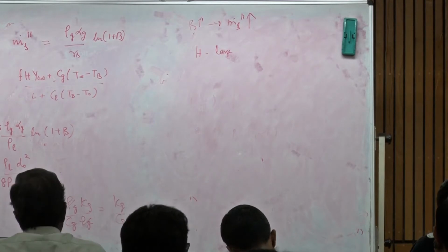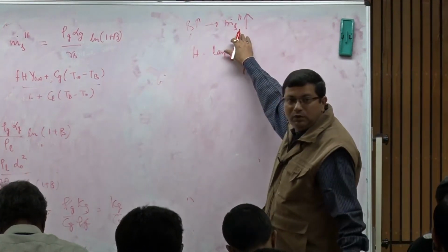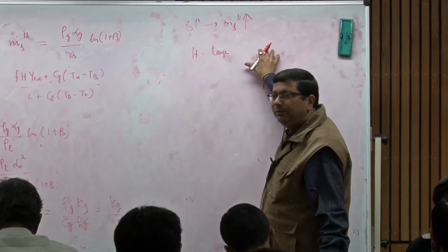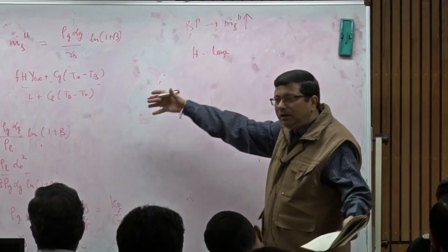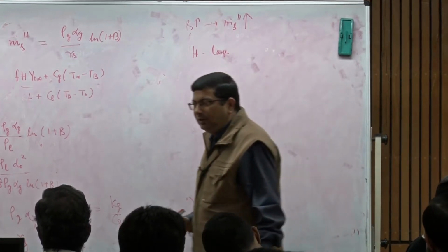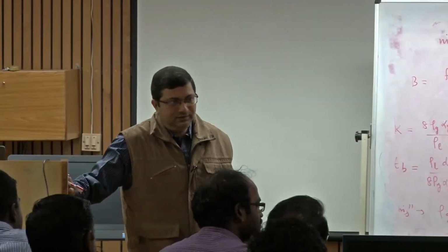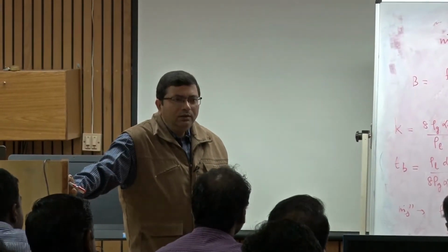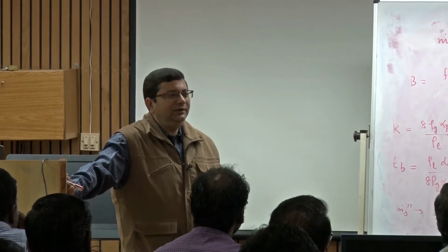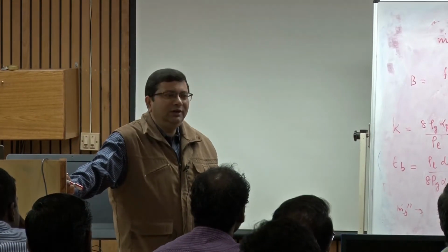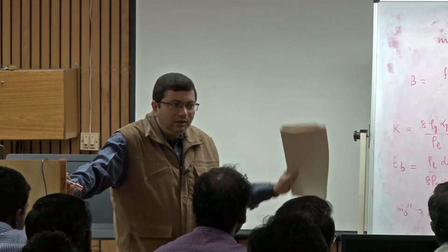Particularly for aircraft application, if m dot s is low, it will take longer to evaporate and burn. That means you need a longer combustor, and for aircraft application the combustor size has to be minimized. That is why for power generation on ground or for gasoline engines, all over the world people are diluting the fuels with alcohol and burning it.